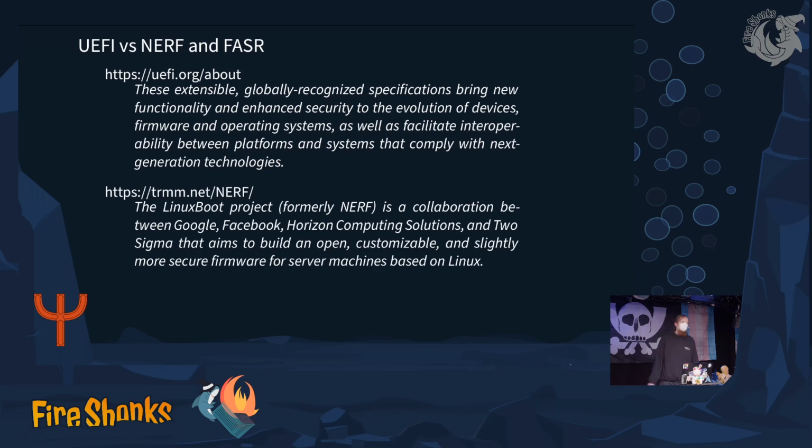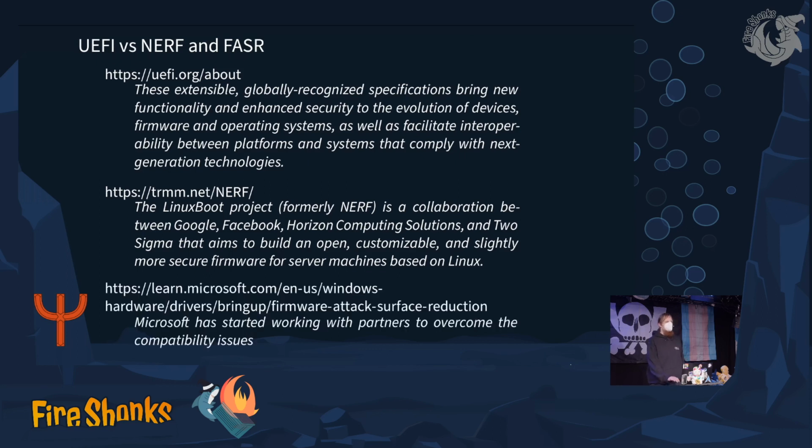Then there are people from Google and Facebook and Horizon Computing and Two Sigma, and they thought, how can we create something from this UEFI stuff and reduce it into something more simple, something that we understand better for our firmware. For example, let's include a Linux kernel. And that's how the Linux boot project was created. It was originally called NERV, the non-extensible reduced firmware. That's where we have this reduction aspect.